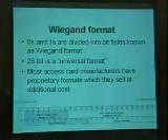The next thing we've got is the Wiegand format. So generally, if you go out into a store and say, oh, I want a Wiegand prox card, it will probably be 26 bits. They'll ask you, oh, what facility code would you like? And that ranges from 0 to 255. And then they'll give you a range of cards, which you can specify quite often. So it's actually 24 bits because you've got a parity bit at the beginning and a parity bit at the end. And that's what makes up a Wiegand ID.